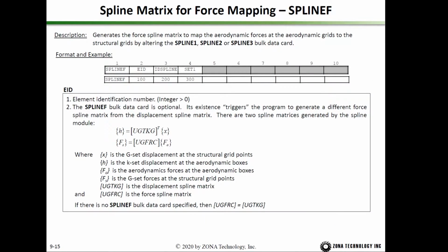And also sometimes when you generate a spline matrix for displacement spline and for the force spline, the strategy to generate those spline matrices may be different. So you want to use this class SPLINEF to alter the structural grid involved in the spline, and to generate a force spline matrix.